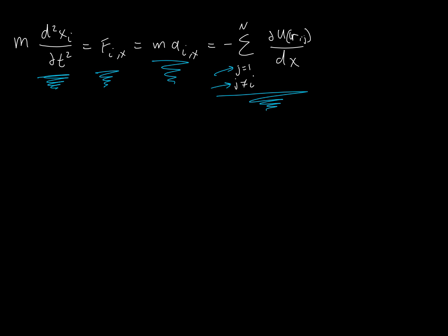Now in any practical system, we typically impose a cutoff distance. If you have a 10,000 particle simulation, we would never be able to simulate anything, because for every single particle, you would have to calculate 10,000 forces times 3 dimensions, and then do that again for every other 10,000 particles. That's just an obscene amount of calculations. And so that's why the pair potentials tend to go to 0 at large separation distance. And so at some point you say, you know what, forget about it. I'm only going to concern myself with particles that are 2 nanometers away. So the cutoff distance is a parameter that you'll control in a simulation.